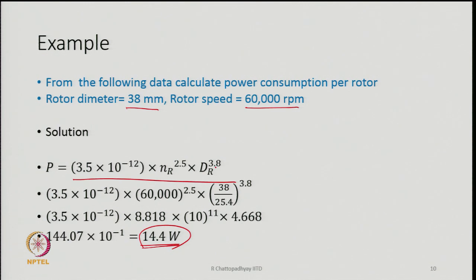So, we are simply using this formula, and what is to be noted here is that the power consumption increases disproportionately, at a power between 2 to 3, actually it lies somewhere there, about 2.5. So, with this increase in speed, the power consumption goes very, very high.